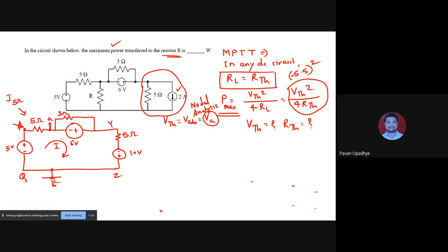Now look at this circuit. Okay, between A and B, you have to find out the resistance. And while doing so, according to Thevenin's theorem, all the voltage sources should be replaced by a short circuit. So instead of the 5 volt, I am showing a short circuit connecting it. Now, moving ahead, here in this case, here was a 6 volt, so short circuited. Then here was a 5 ohm, and again a voltage source short circuited.